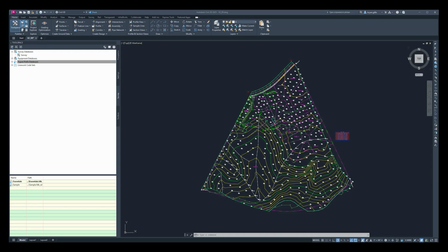And when we're looking at differences in surfaces, primarily what we're going to be looking at is cut and fill volumes. So that's, again, if you're working on a project, how much needs to be removed, how much needs to be added, and how much earth can be utilized within the same project to satisfy those cut and fill needs to create our corridors or our pathways.